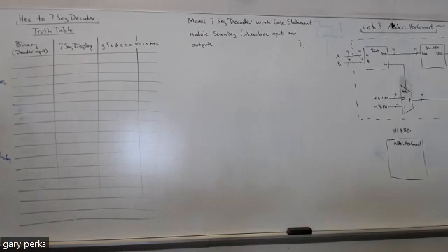So that's why we're putting it here, because the thing it's connected to doesn't have enough oomph, if you will, enough current in the NOT gate. The transistor provides some more current so that when a segment lights, it lights up brighter. It allows more current to flow through each of them.